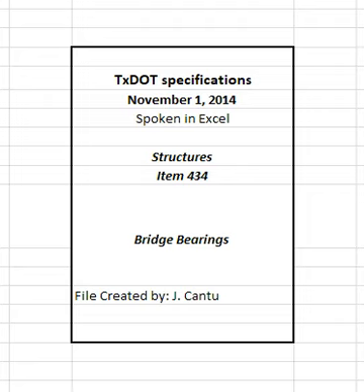3.2.1 Markings. Mark the bearing type on the surface of each sliding elastomeric bearing. The marking must remain legible until placement in the structure. Permanently mark the laminated elastomeric bearing pad with the information specified in Section 434.3.1.1, Markings.